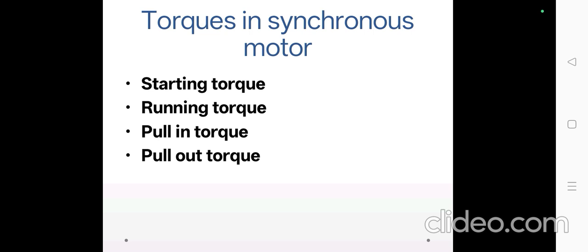Next one is constant excitation. Actually, when delta increases, the magnetic flux lines producing the force of attraction between the two get more stretched. This weakens the force maintaining the magnetic locking, though the torque produced by the motor increases.